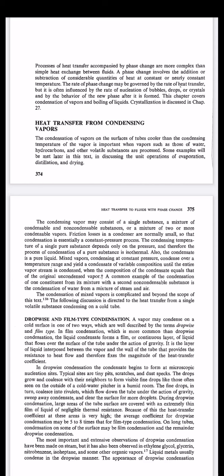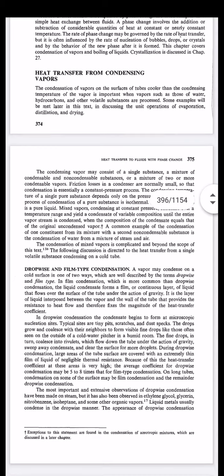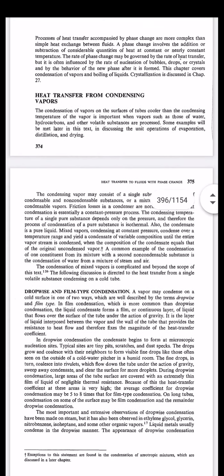So there are two types of condensation of any mixture or any solvent. One is film wise condensation, and another is drop wise condensation. Basically the drop wise condensation is always preferred and expected because the rate of heat flow, the rate of heat transfer, is always greater in the case of drop wise condensation.